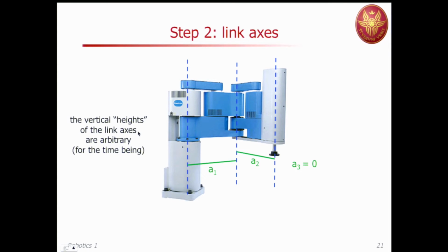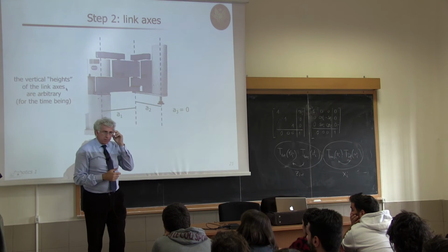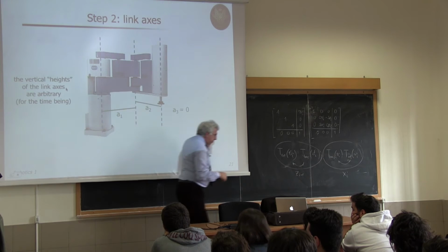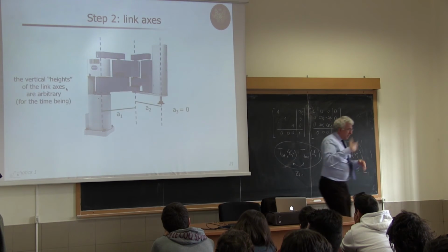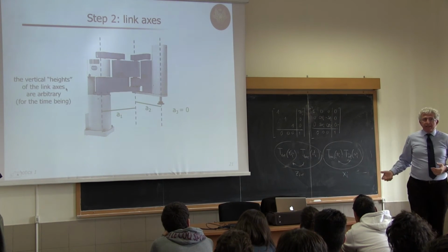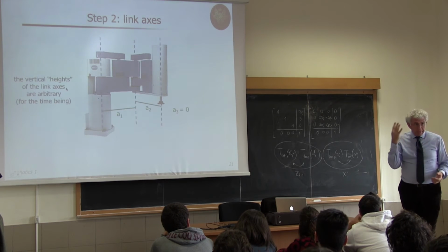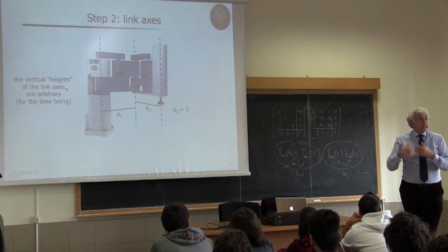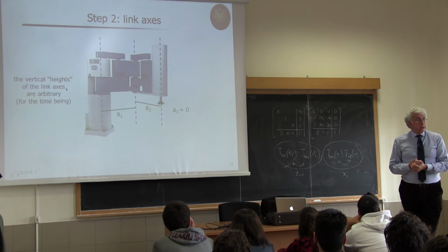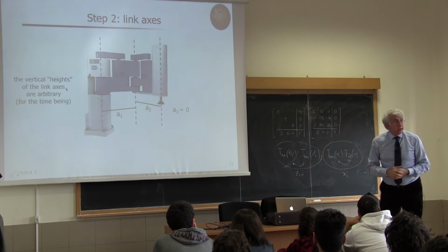Why? Because joint 3 and joint 4 are coincident. So there's no distance, no matter how I compute this. Okay? And then A4 depends on how I choose the last frame, which is the nth frame, frame 4. I know already that there is some ambiguity in doing this, so I'm not writing A4 here yet.